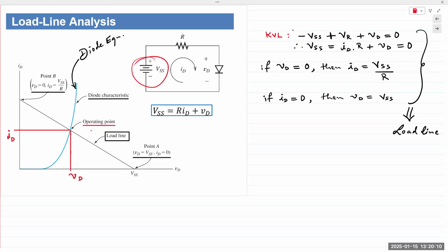It's not possible. So even if you have two devices right next to each other, built at the same time, at the same temperature, even operating at the same temperature, it's never going to be exactly the same. Okay. So there's always a range of values for every single diode, or every single transistor for that matter. There's always variation. But for the most part, they will be very similar within a certain range of values. Okay. So you could take one diode out from this circuit, plug in a second diode in its place, and have pretty much exactly the same response as you see on here.